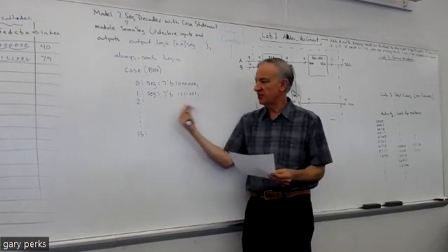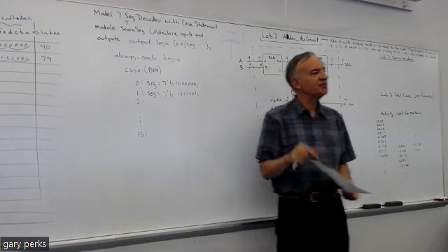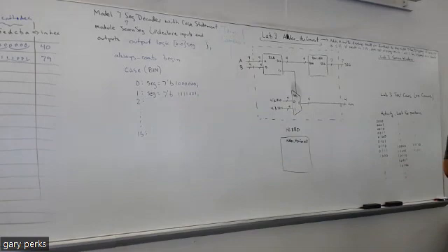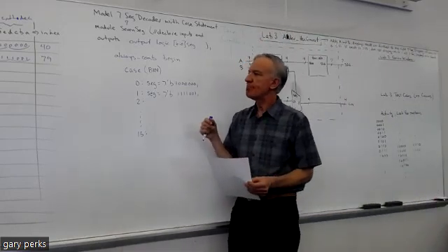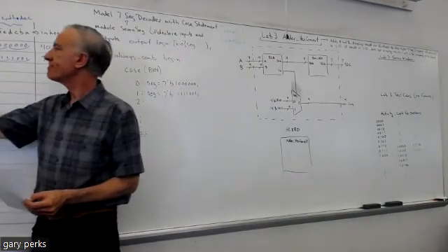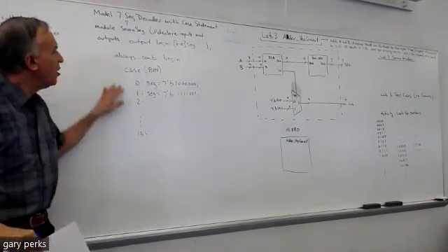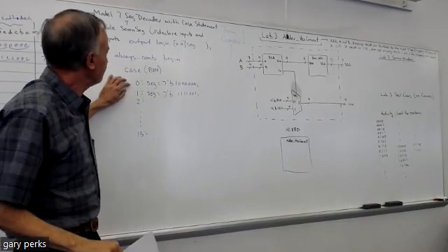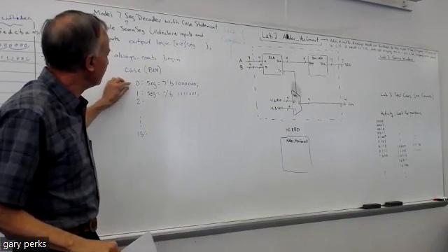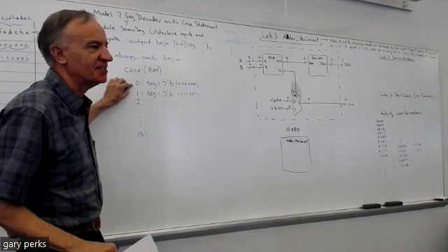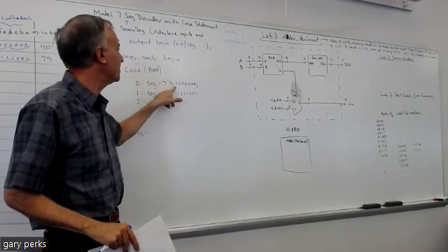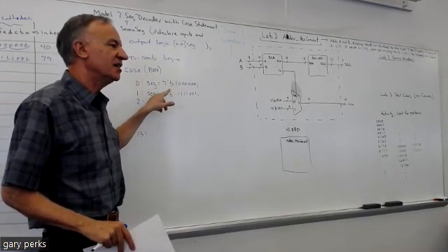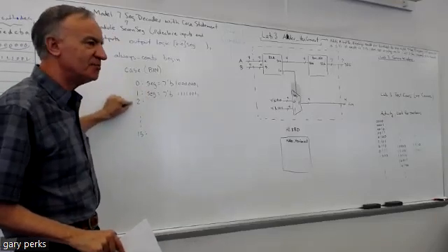Any questions? Again, you can fill in the rest, it's just from the truth table. So does SystemVerilog automatically translate the input into base 10 for you? Because we have an input of 4 binary bits, and then our cases are all. Well, I think in a case statement in SystemVerilog, whatever number you put here on the left side of this colon, it just takes as base 10. Then you got to tell it what the output is equal to for that option, and then you can tell it the base here.